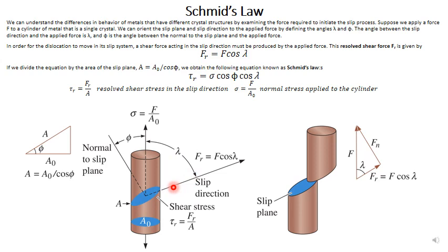That's because some slip directions are not on the same plane. The slip occurs in a direction, but the direction is not on the plane. It is deviated from the plane in a different direction, as we have seen in the previous slides. Thus phi plus lambda is possibly equal to 90, but not necessarily.